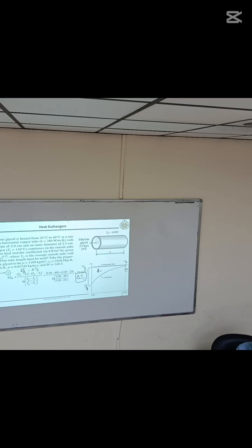Here, yes, all temperatures are known. TG, which is constant throughout, and TI and TE, which is changing 40 to 25. Okay, so that will give us delta TLM 77 degrees Celsius.